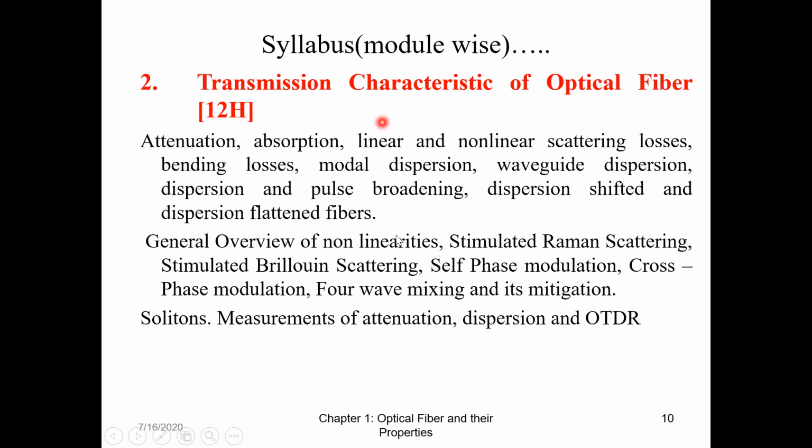are studying over here. This measurement is the typical measurement. ये हम लोग lab में भी करते हैं, measurement of attenuation and all, वो cable को काट के and all those things, which is a destructive technique. But in actual field, we cannot cut the cable to measure attenuation loss, dispersion loss. So in the field, we use the device called OTDR.